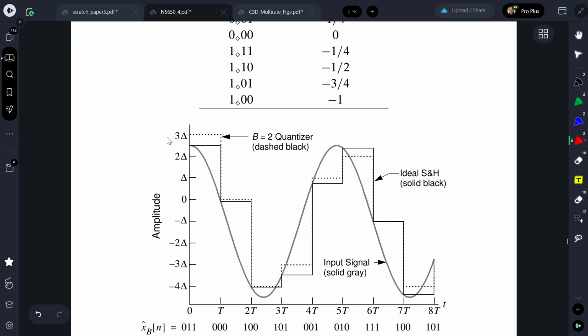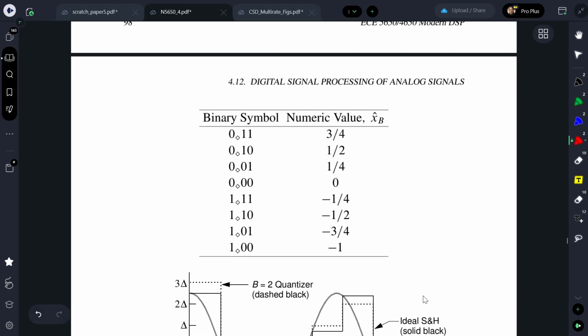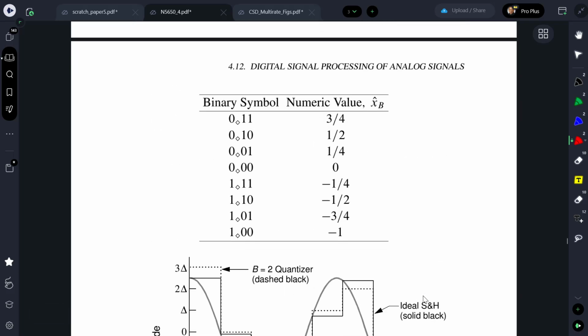I drew this out by hand, and I don't remember if I took all the cases into account, but here it's looking like the level goes up or the level goes down. So you're creating error that's symmetrical about the nominal quantized values, and those are these values right here for this 3-bit quantizer. There are 8 total values in here. So how do we model this?